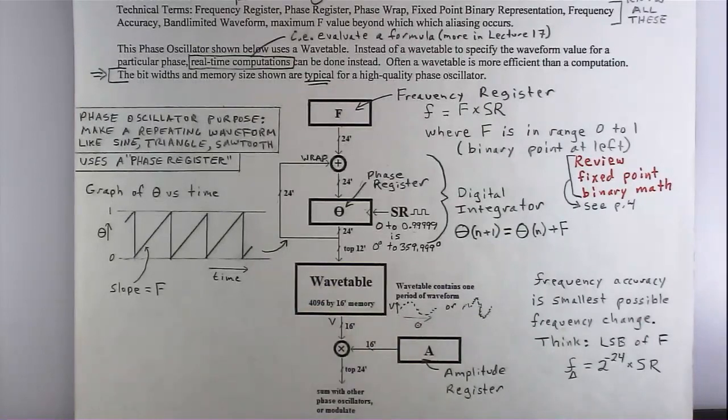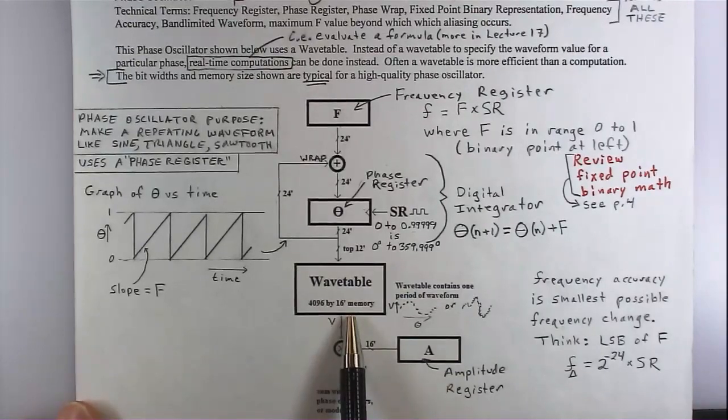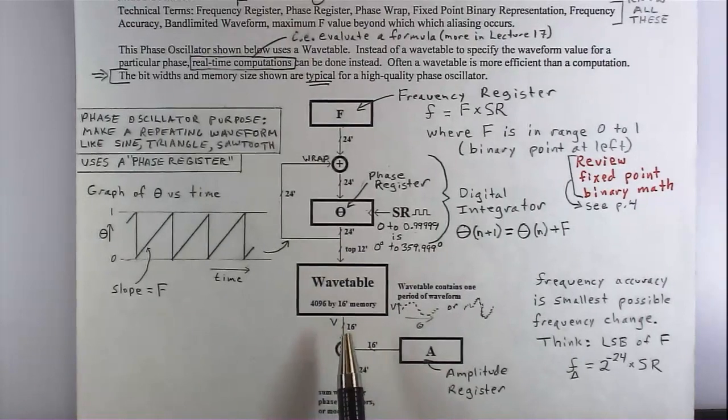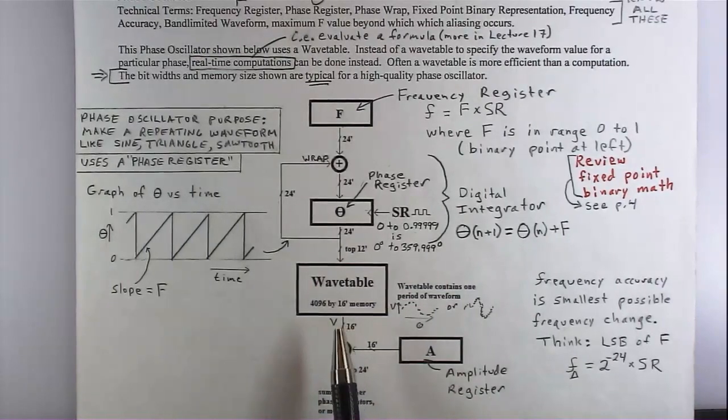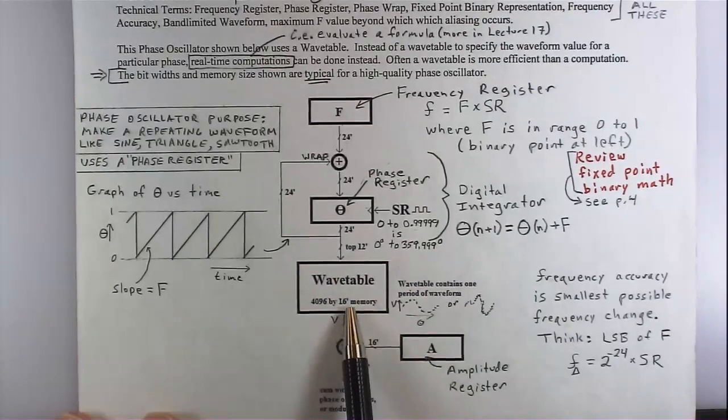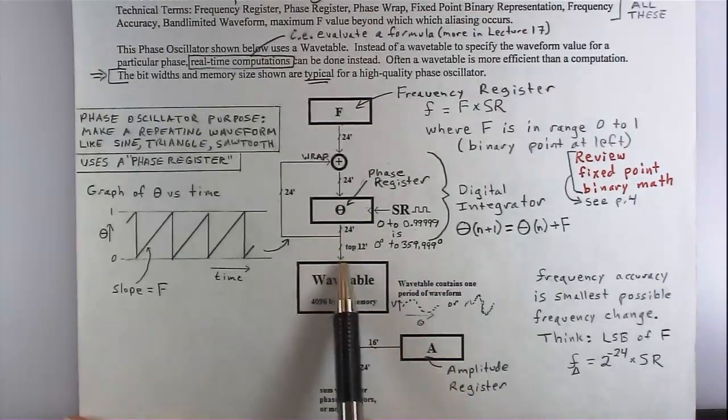If you're doing wavetable synthesis that is good quality, there's reason to keep it short, unless you have infinite memory to waste. It doesn't gain you a whole lot to make the wavetable longer. Because this is a band-limited thing in here, almost always, if you really want a longer wavetable, you'd be way better off just doing linear interpolation between values on the output. It's not that important, just something to mention. People always like to throw memory at things because they bought gigabytes of memory in their system, but it doesn't really gain you much. Okay, so here's the phase register, and then we only use the top 12 bits.